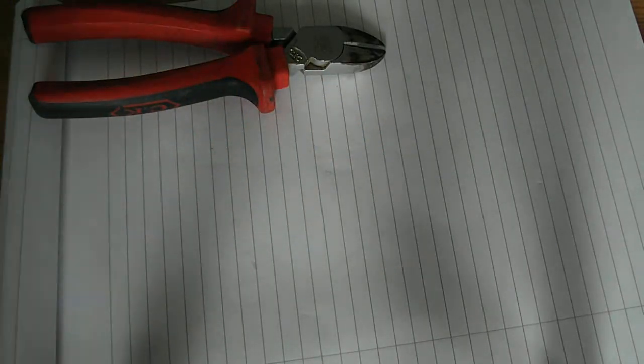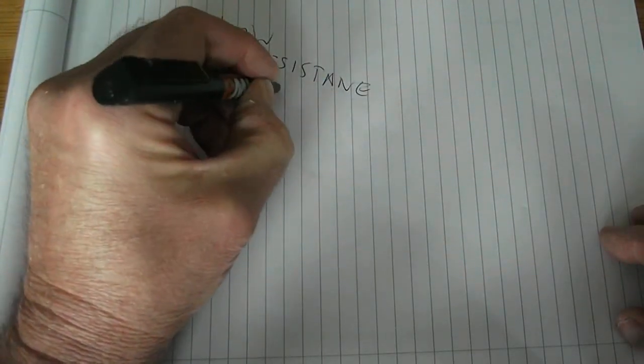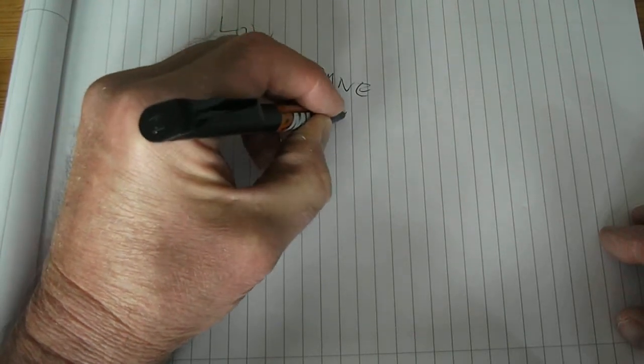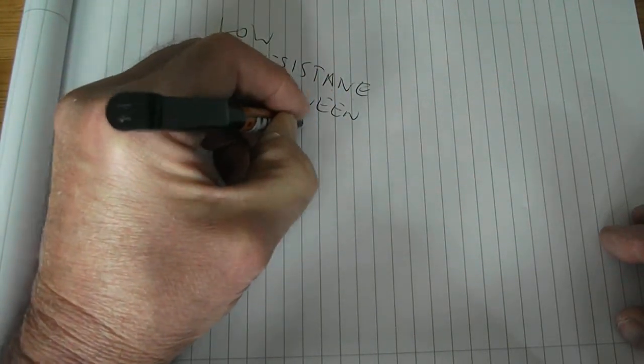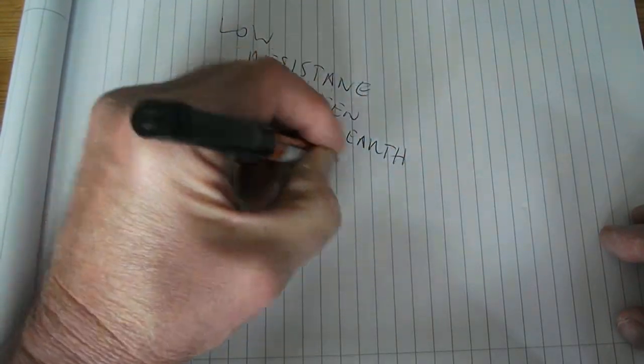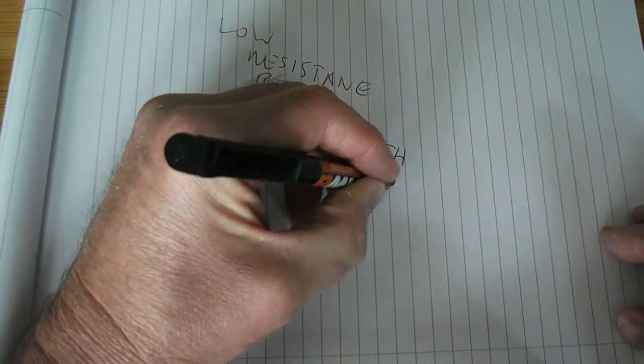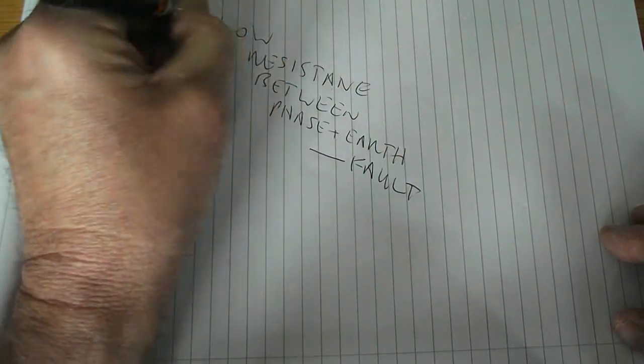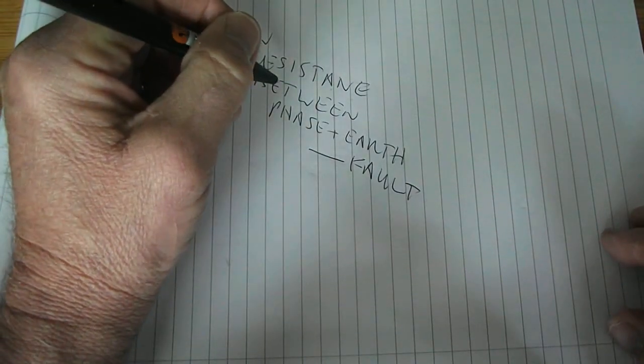So for the purposes of this course, you need to remember that low resistance between phase and earth is a fault. It's low resistance. Okay.